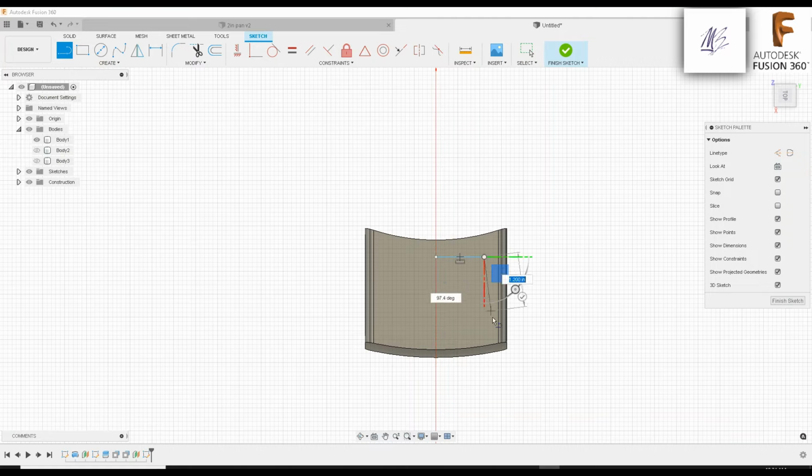All right. We're just going to create, again, some rough dimensions here. Just kind of do like that. There we go. All right, good. Press enter. Okay. Now let's mirror this. You want to left click it and hold the shift key at the same time. It's going to illuminate all the segments. Or you can double click one segment and it's going to highlight everything. So that's what we just did. All of the segments, the lines that were created, highlighted.